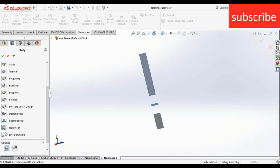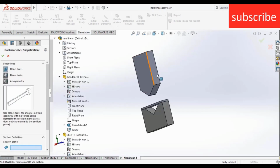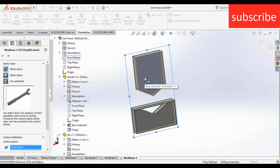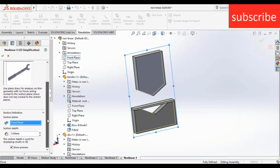Now go downward, select non-linear, use 2D simplification, click OK. Now select the front plane. I hope you now understand why I am choosing the front plane. If I choose any other plane, then there is no symmetry in the drawing and it will be totally wasted.